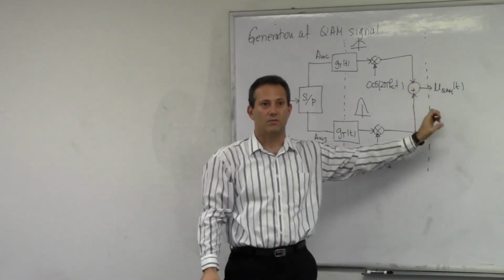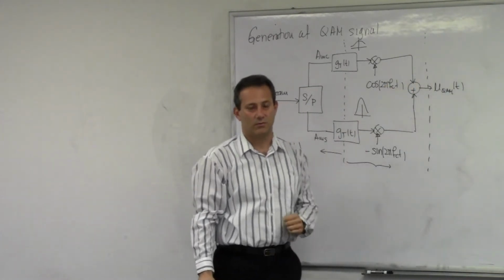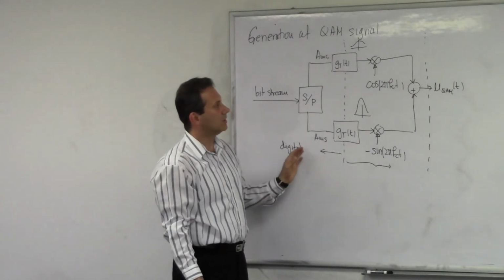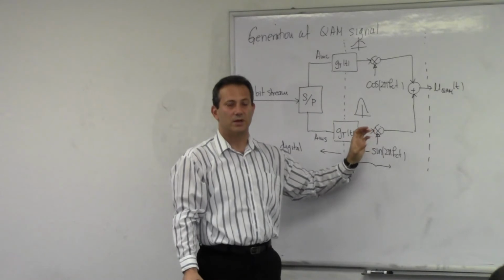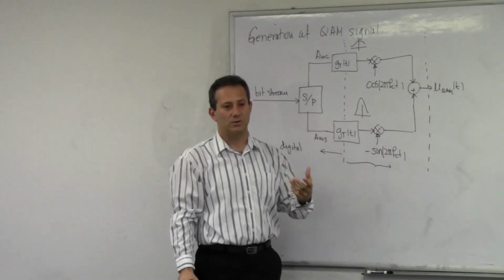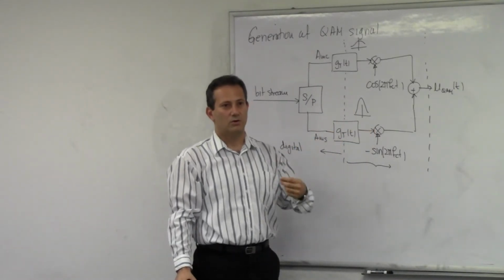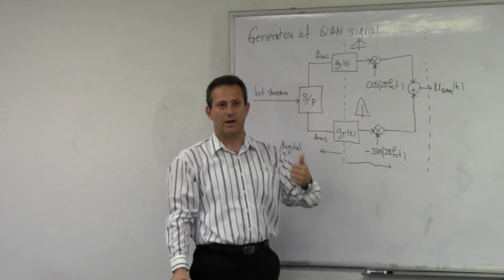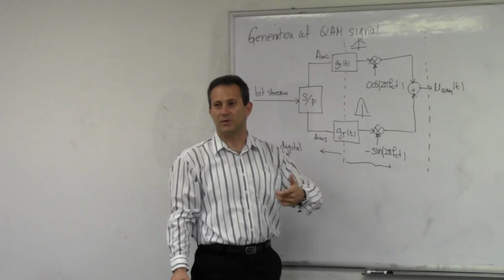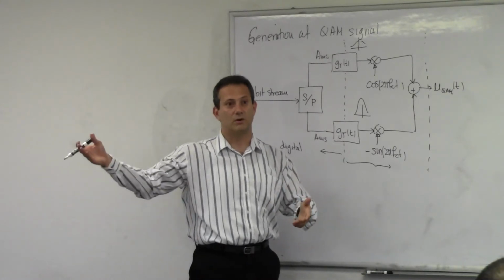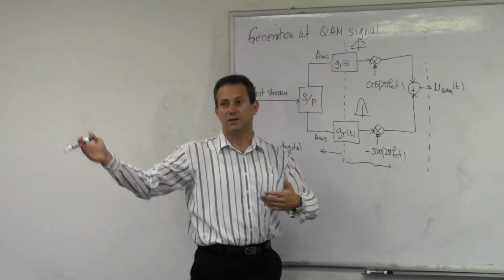It generates the form, and then you translate that form to whatever is the operating frequency. There's a great benefit in this because you can do a lot of it in pure numbers. And when you do it in the digital domain, you're absolutely in control of your accuracy. There's no aging of the components. If the software works today, it works tomorrow, it works 10 years from today in the same way.